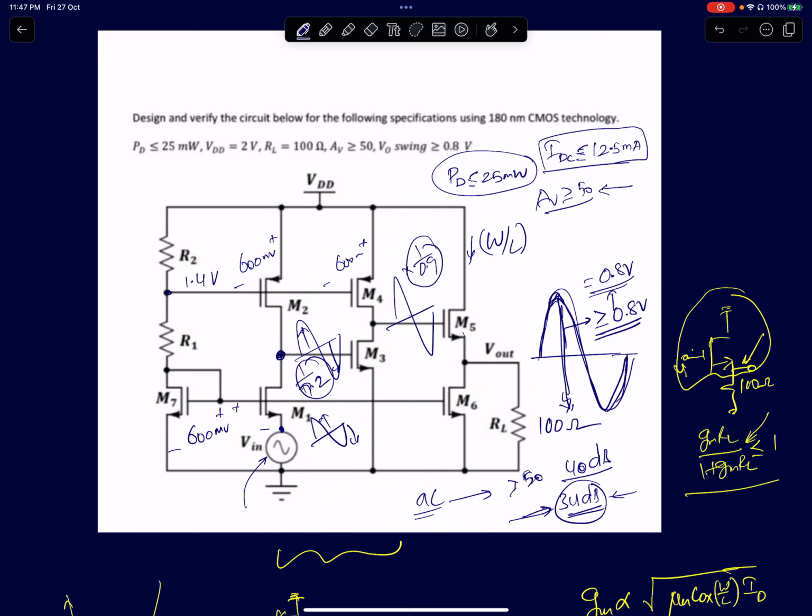Mind you, I've given you one approach to design the circuit and some important points to keep in mind when designing. That's how analog engineers think. Before you start a design, you know intuitively how much current you have to burn to get a certain GM, and keeping that in mind, we can design. I just told you to choose 100 microamps or 50 microamps for each of the stages, and not worry much about how you are going to get the gain.